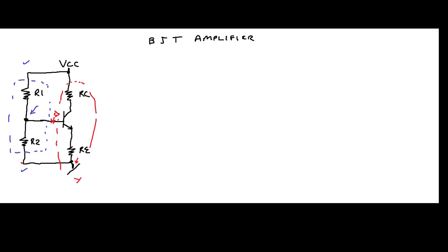Well, basically, if we're going to calculate it, your Thevenin voltage, you already know this, is simply going to be R2 divided by R1 plus R2, times VCC. Now that's pretty straightforward. You're used to that. Remember, disconnected, no current flowing, that's going to be your voltage there. Now, let's talk about this. What about